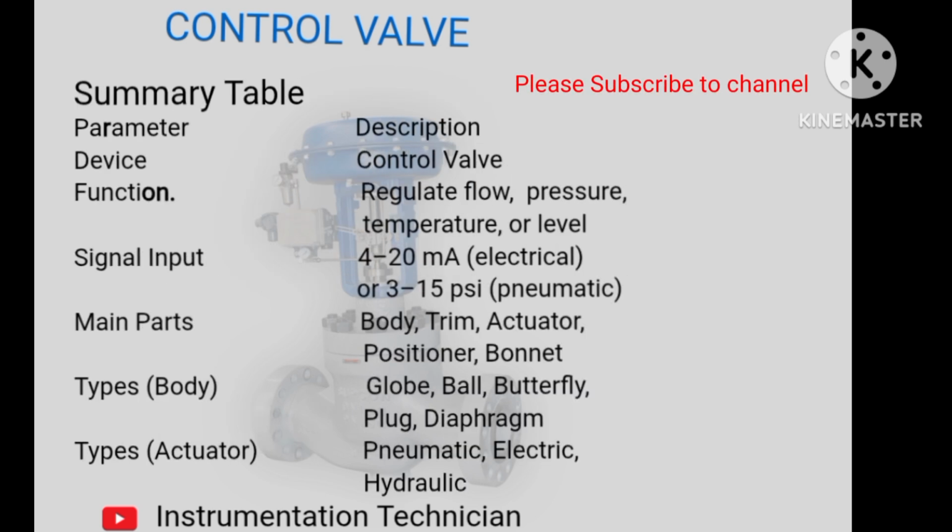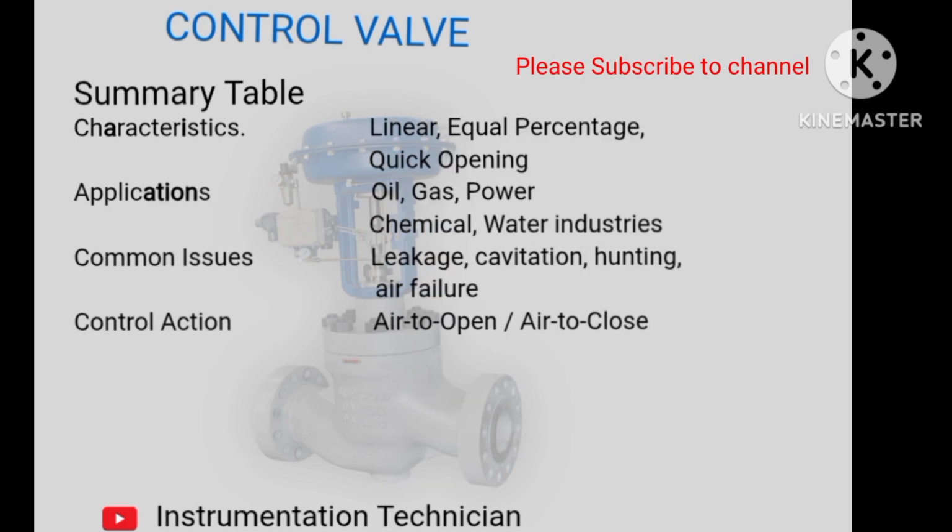Summary table. Parameter, description. Device: control valve. Function: regulate flow, pressure, temperature, or level. Signal input: 4-20 mA electrical or 3-15 psi pneumatic. Main parts: body, trim, actuator, positioner, bonnet. Types, body: globe, ball, butterfly, plug, diaphragm. Types, actuator: pneumatic, electric, hydraulic.